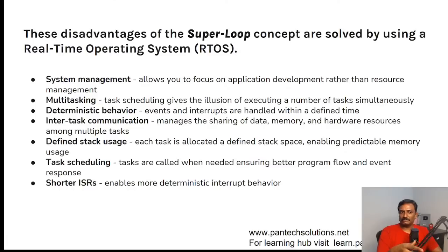But with the super loop concept, most embedded systems are based on the super loop. They just have a simple while loop which executes the tasks one by one. That will not support multitasking. You definitely need an RTOS for multitasking.